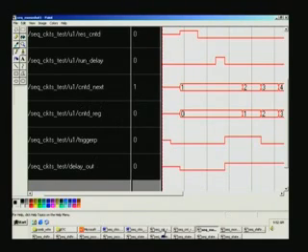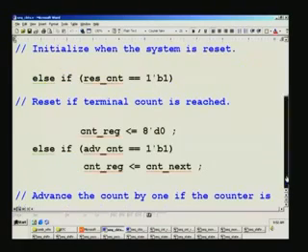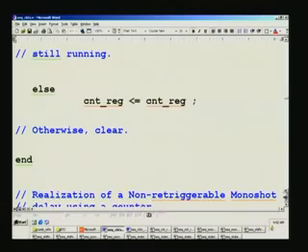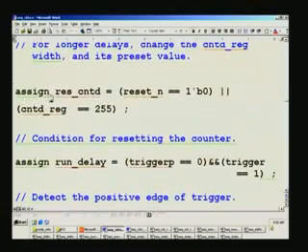So if you look at the code for this, here we have combined two resets into one statement, that is power on reset here and also counter D being equal to 255. And when any of these happens, this is an OR here, so this will go high.